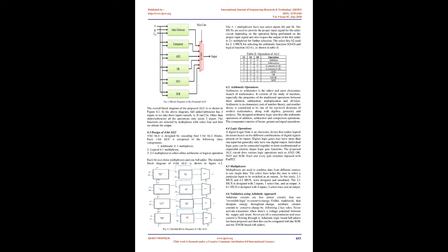Beyond the technology-driven benefits offered by FinFETs, circuits can also benefit from the double gate structure of FinFETs to further optimize power and performance. FinFET leads to some interesting designs by means of etching out the top part of the device, which achieves independent gate structure.